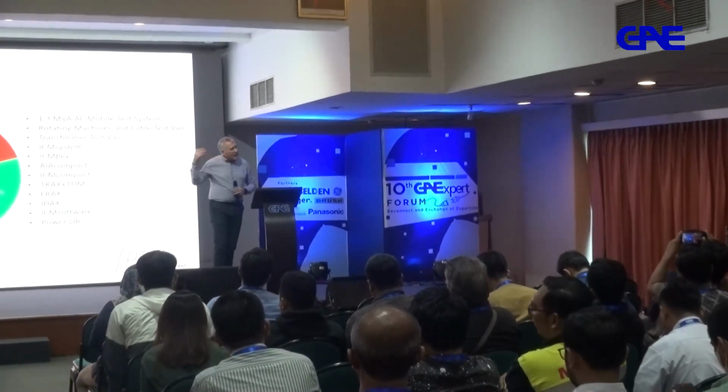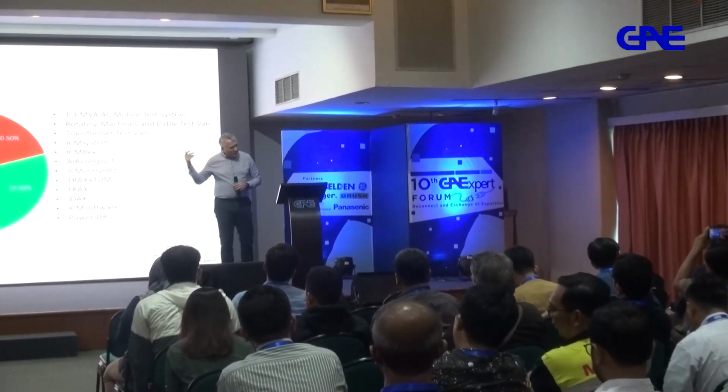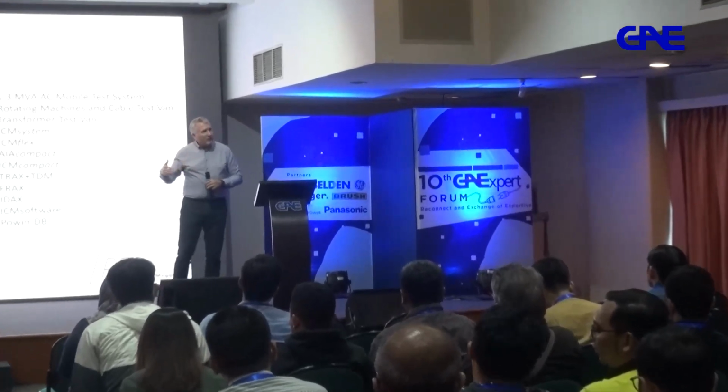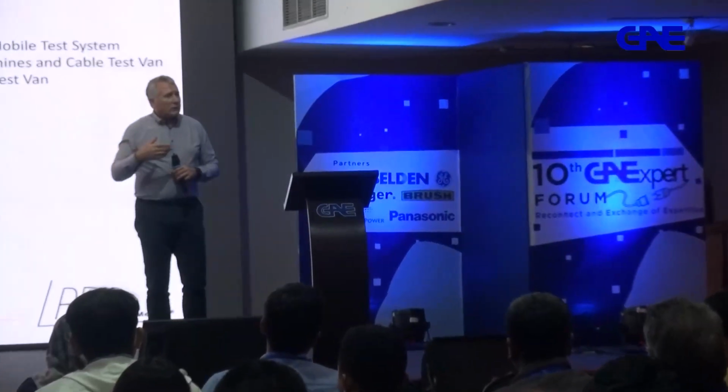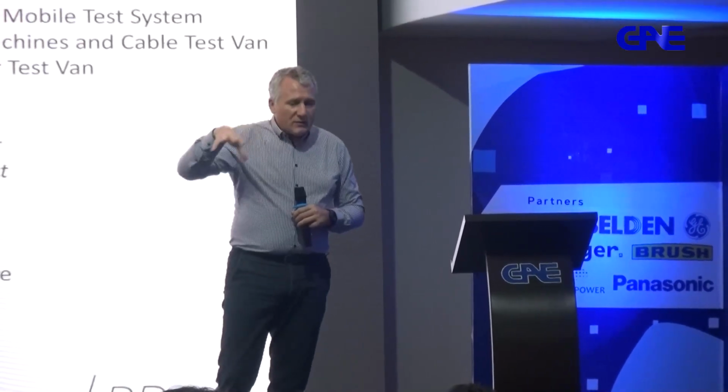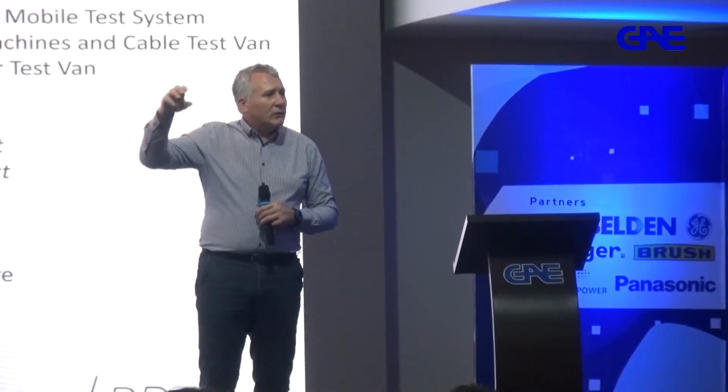But when you have a big asset, an expensive asset, like a transformer, like a GIS, you want to go maybe two steps forward. One step is to actually understand the type of fault you have and then localize it. So let's say in the case of a transformer, you just take that winding out and send it to the factory, not the entire, how many tons transformer.